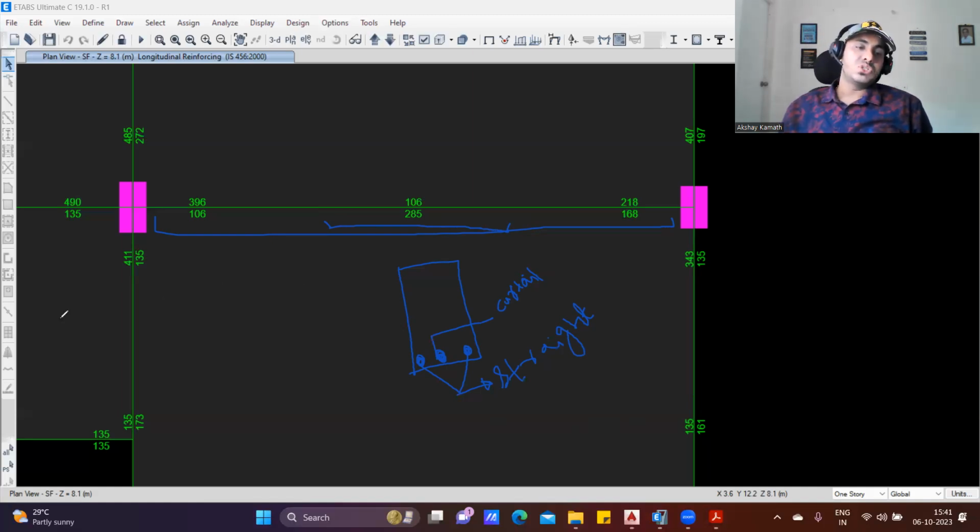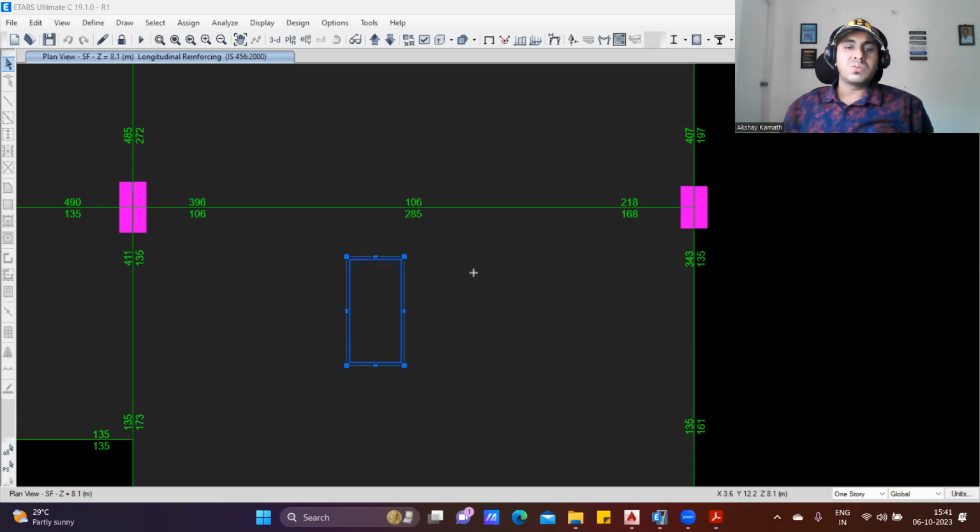Now, once we have understood everything, I'll put all the detailing. Now for a single beam, I taught you, right? Now what I'll do is I'll put that in a cross section part, both top and bottom. So top we were supposed to provide how much? 12 diameter. Top we were supposed to provide 12 diameter 1 bar. Then again 12 diameter another bar here.